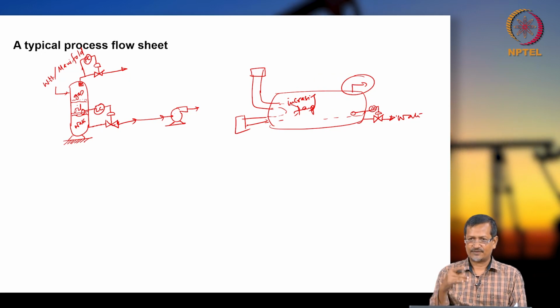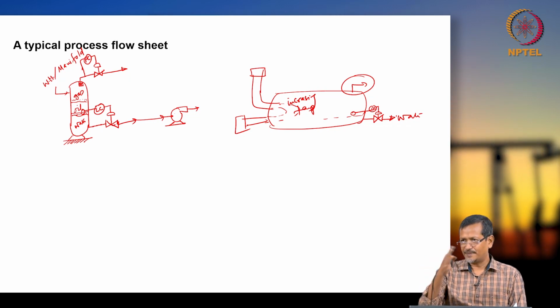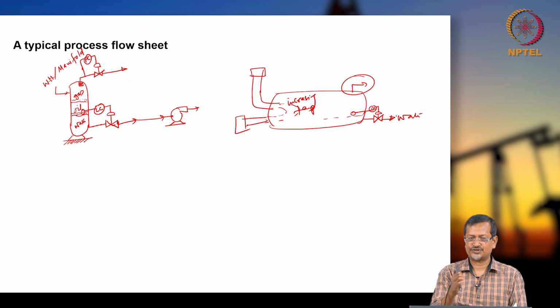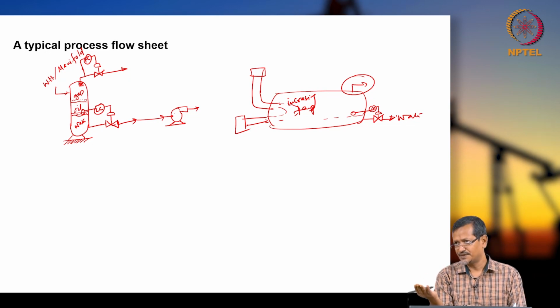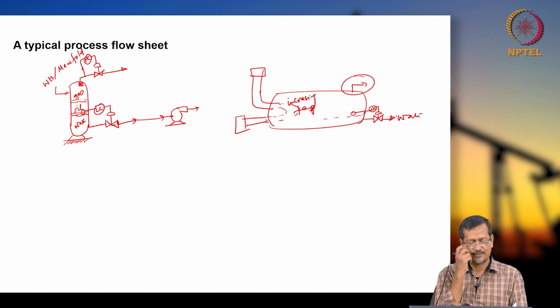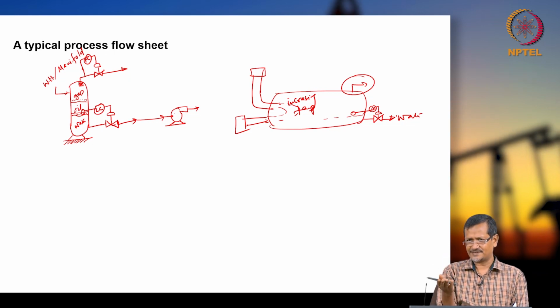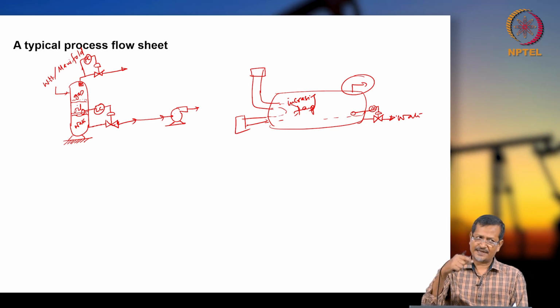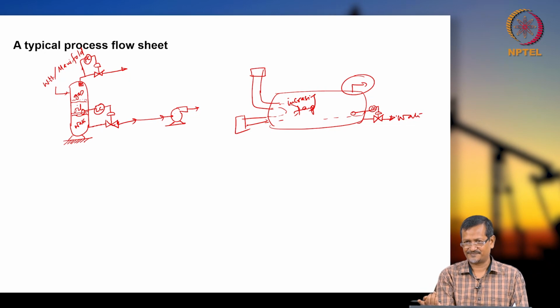So in every case you have to use a controller, so that you can control your pressure and flow rate, and maintain your pressure in certain sections. You can use some pump, or in certain sections you can use a compressor. In many places there will be low pressure gases, low pressure wellbores. In that case maybe you have to increase pressure using some pumping or compressor mechanism.